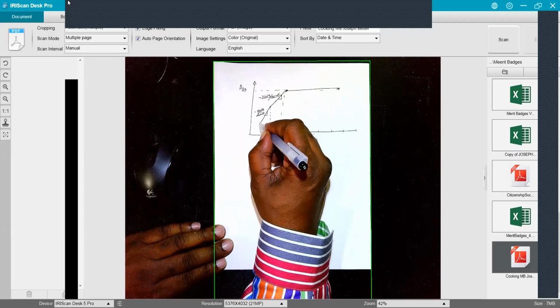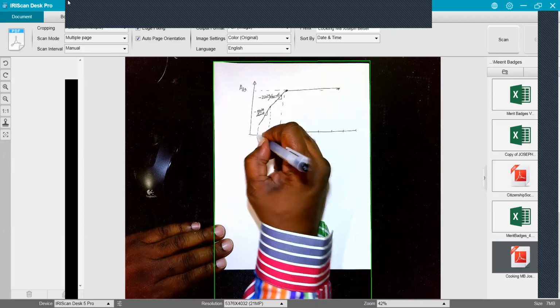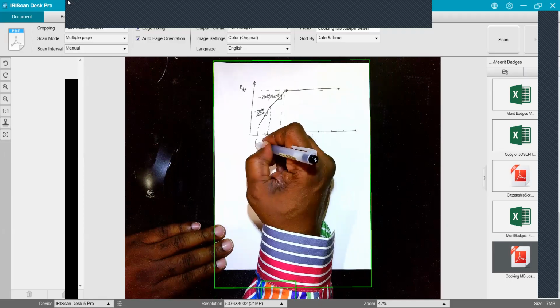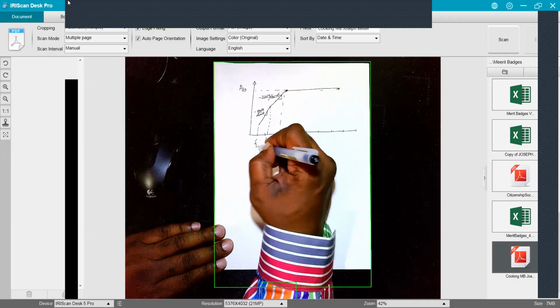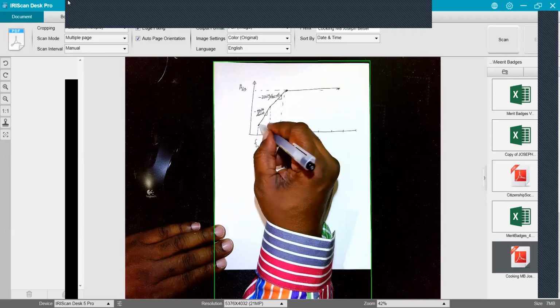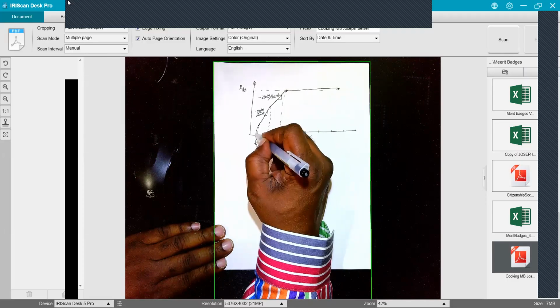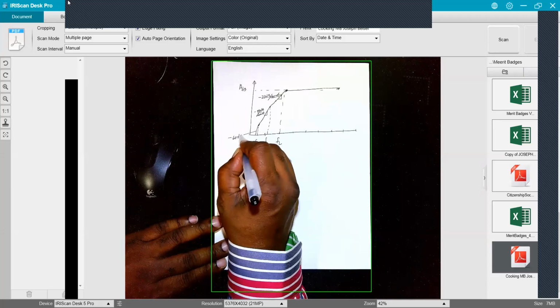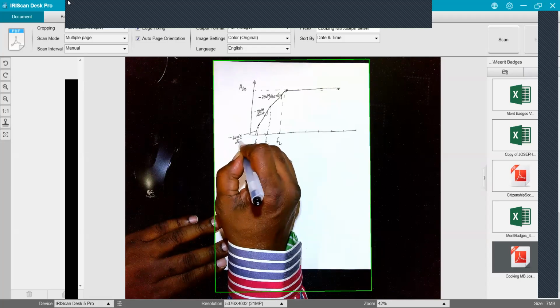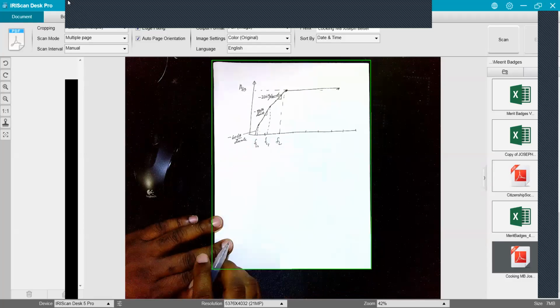And it'll continue like that until we get to our third pole, which may be located here. And then they'll roll off at minus 60 dB per decade.